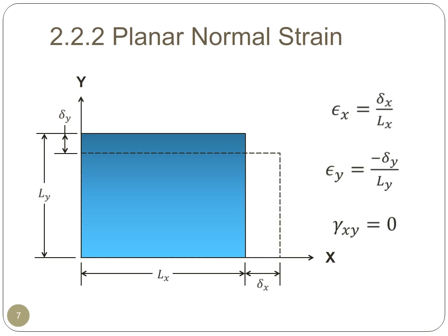In the planar member as shown here, we can describe the strain along the x and y axis of the rectangle. Strain along the x-axis is defined as the change in length along the x-axis divided by the length along the x-axis. For the strain in y, we have the change in length along the y-axis divided by the original length in the y-axis. Using this convention, a positive strain is always defined by increasing length, and a negative strain is always defined by a decreasing length. And so we have adjusted the equations to match this convention.